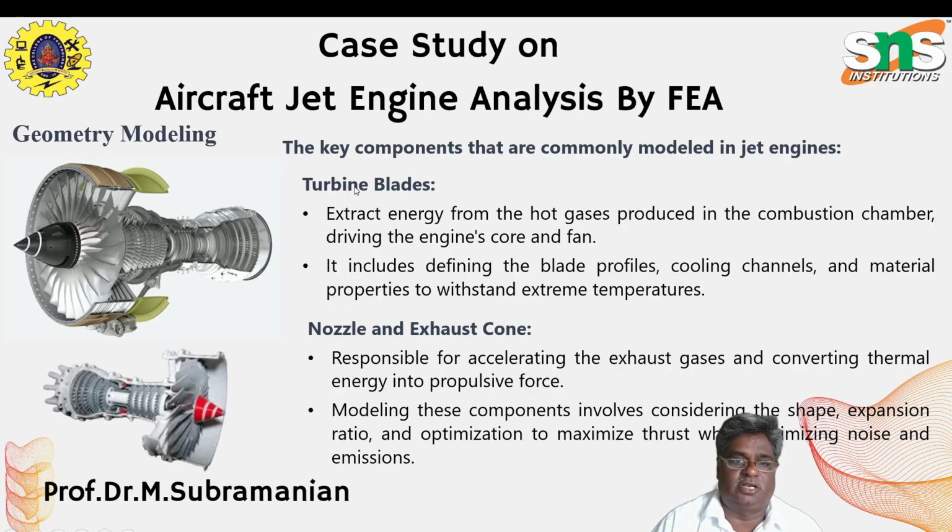The next key component of the aircraft jet engine: turbine blades, and nozzle and exhaust cone. Turbine blades extract energy from the hot gases produced in the combustion chamber, driving the engine core and fan. Modeling includes defining the blade profiles, cooling channels, and material properties to withstand extreme temperatures.